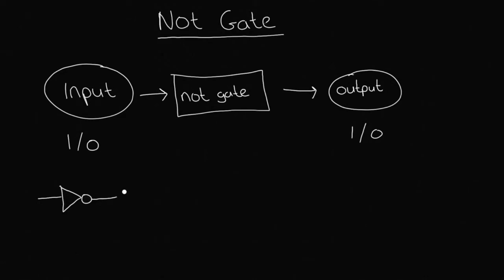Now just keep in mind, with this type of gate, the NOT gate has only one input and one output. In some of the other gates that we'll be discussing, our AND gate and our OR gate, we can have multiple inputs. We'll still have one single output, but we can have multiple inputs. So for our demonstration videos, we'll be using 2 inputs for our OR gates and our AND gates. Now keep in mind, you can have more than 2 inputs for your OR gate and your AND gate, but for our NOT gate here, we're just using 1 input.